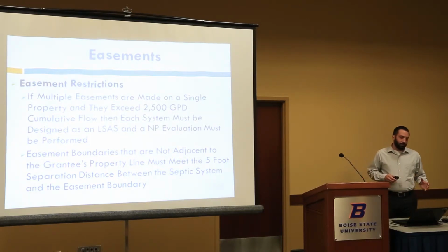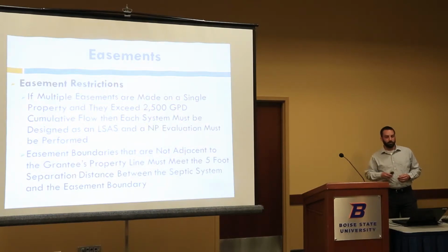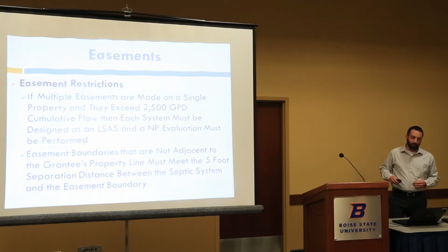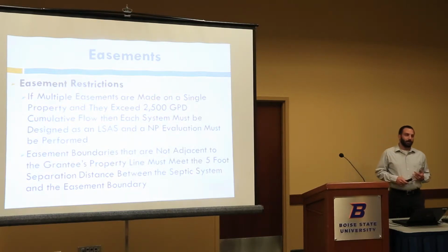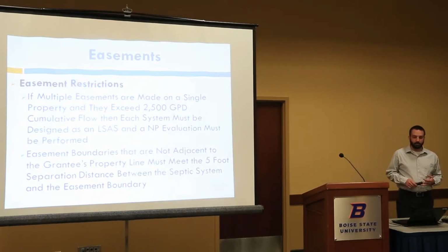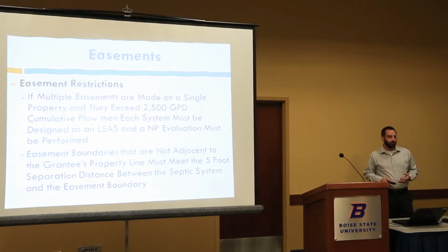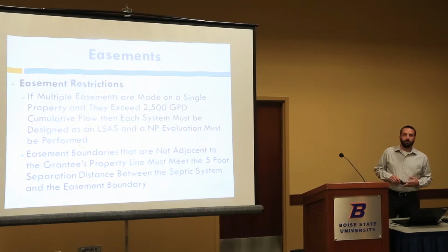And that goes along with what the subsurface rules have as a definition for the large soil absorption systems, and that it covers an entire project. So it can be multiple different systems, and if all those systems are part of the same project and they exceed that 2,500 gallons per day flow, then it's a large soil absorption system. So at that point, the developer or the applicants have the decision to make of whether they combine that into one big LSAS, or they're going to leave it as individual systems for each property. Either way, all the drain fields get pressurized. There's 2 of them installed with a replacement area for a third, following the large soil absorption system rules.